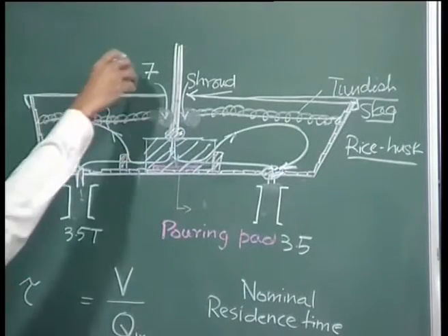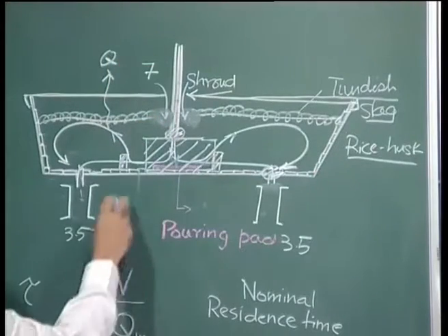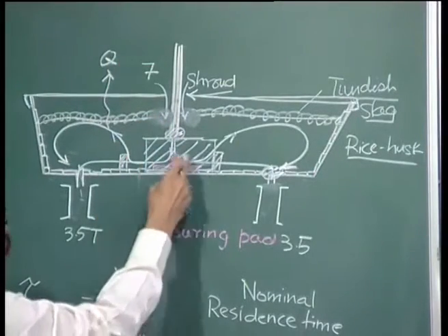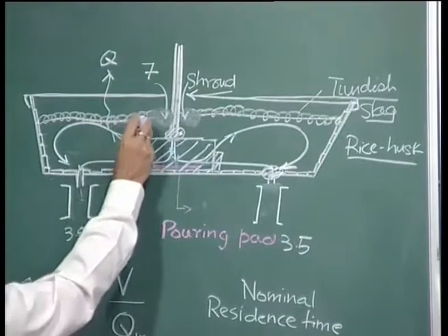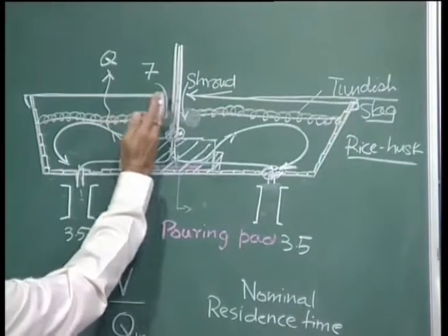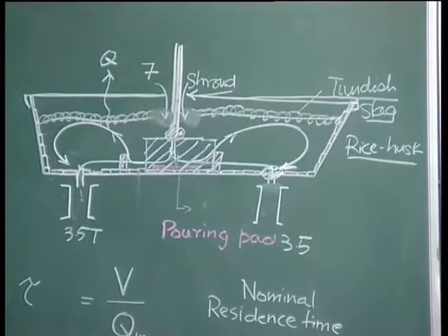So, the submergence of the shroud into the melt, okay, the geometry of this particular region, and the flow modifiers in these regions are very, very important in order to control turbulence, in order to prevent any extensive rupture of the slag layer, or even slag metal interaction.